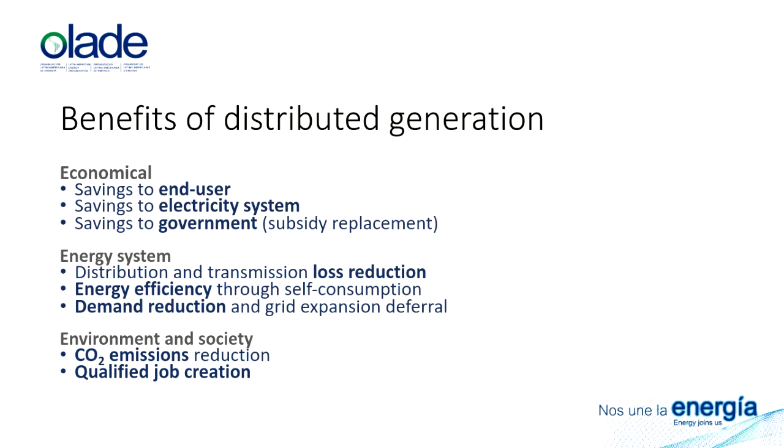From the energy perspective, as we discussed, and it's obvious, you have loss reduction in distribution and transmission networks, because the electricity doesn't travel as far. Even if this is done in low voltage grids, the energy that's self-consumed by the user, of course, has almost negligible losses, but the energy that's injected to the grid is also consumed by neighboring users, so the losses are minimal.